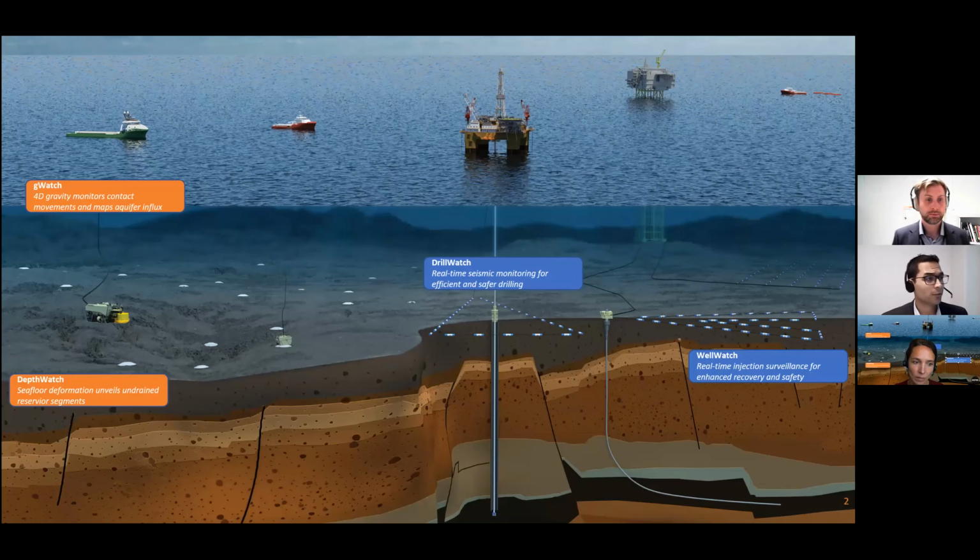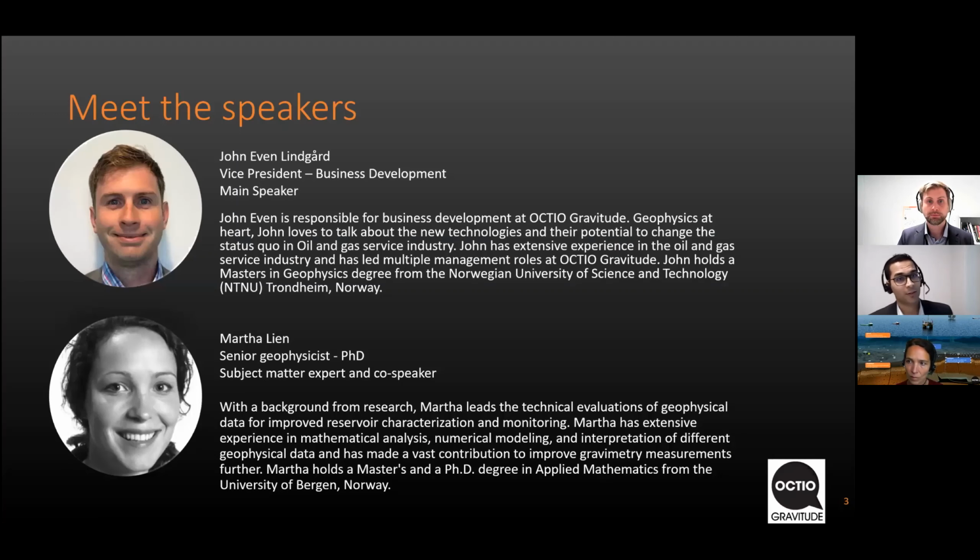The focus for today is the GWatch side of the business, which is on the left-hand side. And we have two key offerings. GWatch, which is 4D gravity measurement sensitive to mass changes within the reservoir, as well as the Depthwatch, which is basically dealing with the seafloor subsidence due to reservoir compaction. Combining these measurements provide a time-lapse idea on how the reservoir is behaving based on production and helps us to improve reservoir monitoring and management. And the key message here is these services provide similar value as 4D seismic at 10%, or 1/10, of the cost. Next slide, please, John.